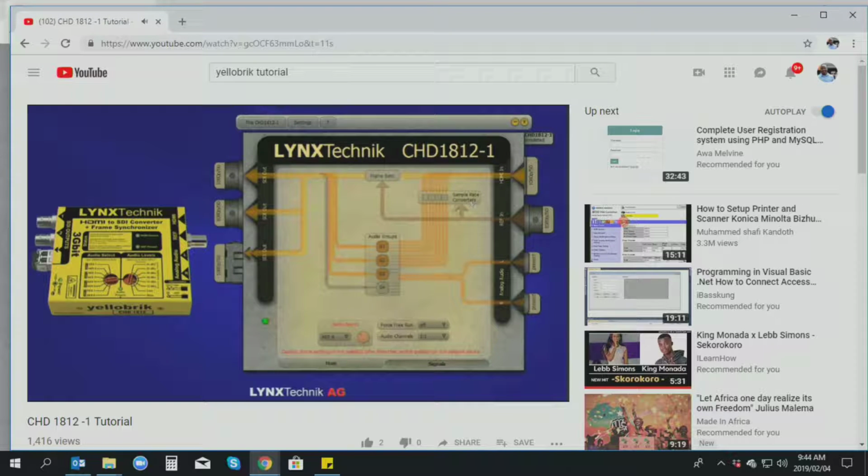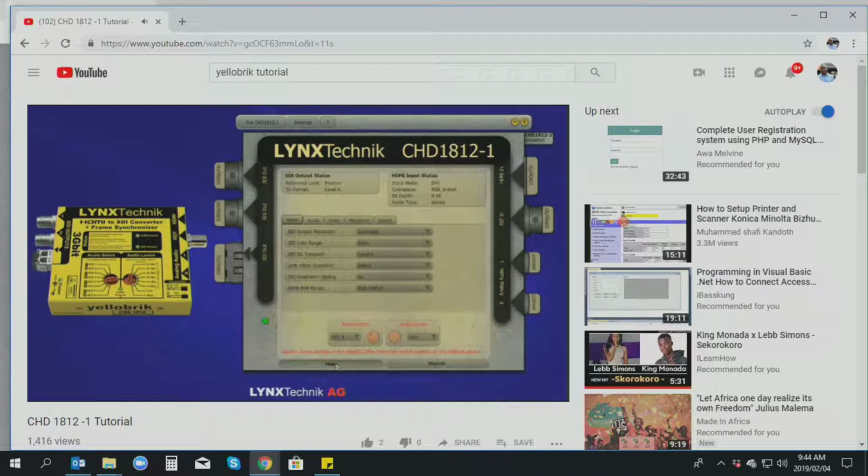So that basically covers the module. As you can see, it's a very useful tool to configure the module. The important thing to remember again is this LED. It always tells you what's going on. Green means good. Amber means some settings have been made internally, so it might not be doing what you think it should be doing. And red means there's a difference between these physical switches and what's set in software. Aside from that, that pretty much covers the yellow GUI and the operation of this module.